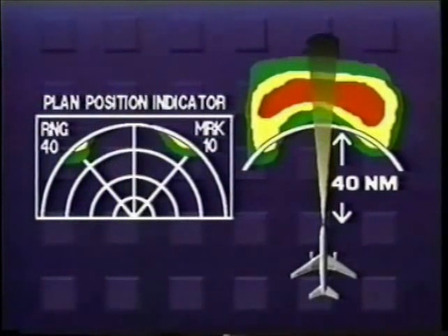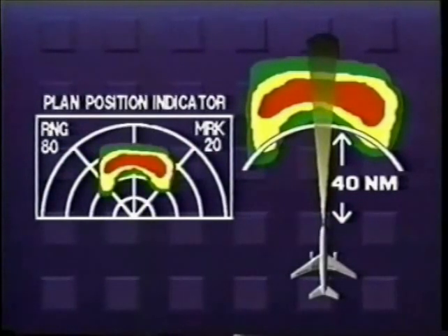A blind alley or box canyon situation can be a dangerous trap for pilots that habitually fly with the radar on a short range of 40 nautical miles or less. The short range returns show a corridor between two areas of heavy rainfall. The long range setting shows the trap. Always switch to the long range before entering such a tempting corridor.